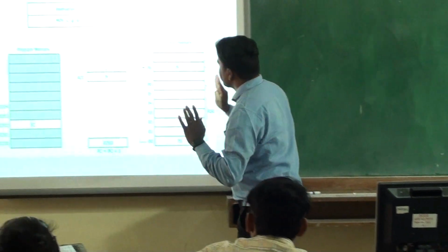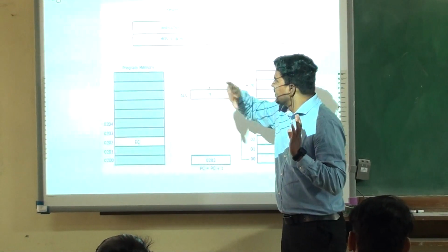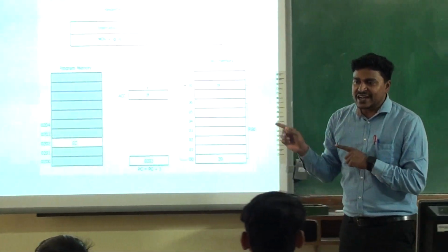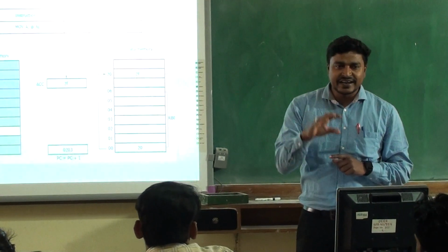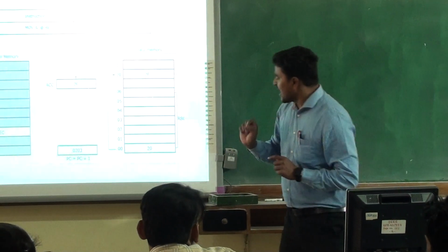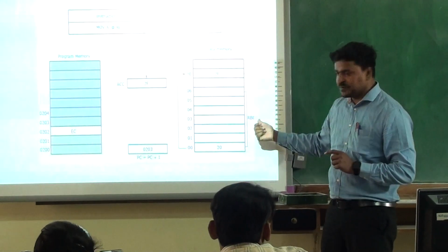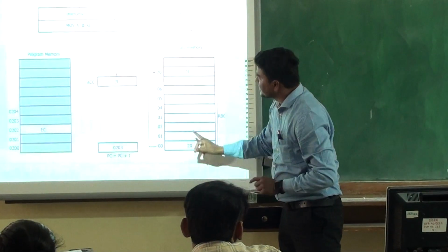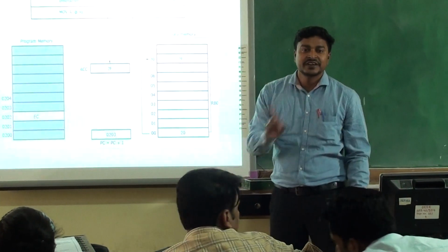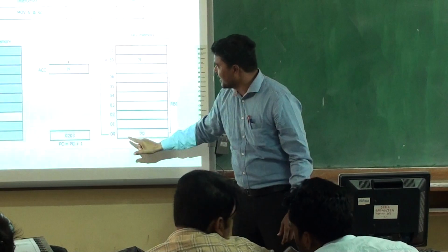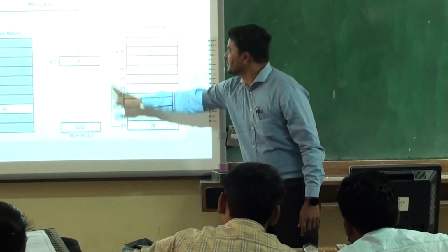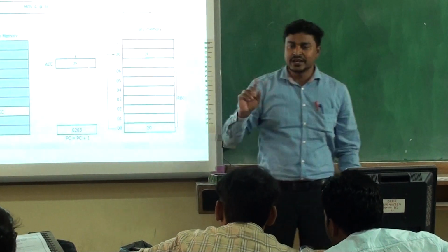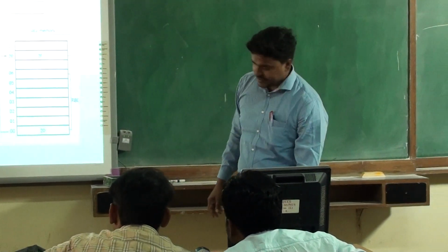Look here, we are writing MOV A, @R0. That means R0 contains the address of the particular data. In the RB0 bank, R0 is the register containing the value 20, which is the address of the data. When we access it, it will go to location 20, where the data is, and it will be transferred to the accumulator.